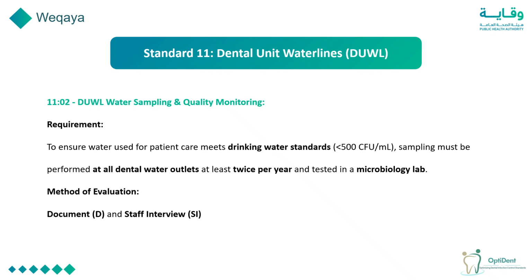Substandard number two, the water sampling and quality monitoring requirement, is to ensure water used for patient care meets the drinking water standard, which is a quantitative, not qualitative, test: less than 500 colony forming units per milliliter.